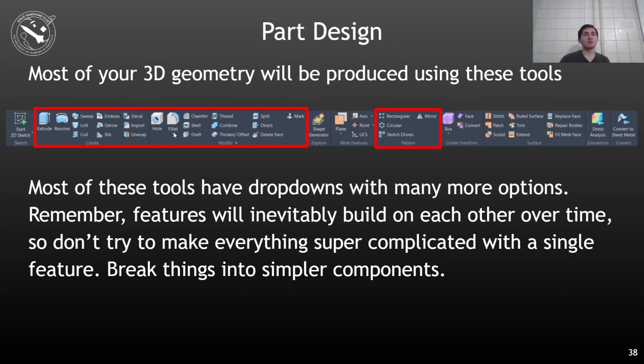There's also this fillet tool. Pretty much everybody has a phone, which I'm pretty sure is everybody here. If you look at your phone, you have these curved edges on the corners. That's a fillet. It's something to keep you from having a sharp edge at the corner of something that can cut things or scratch things. You can also have a chamfer, which is very similar, except rather than having a round corner, it's just some flat cutaway. It's a little bit easier to manufacture.